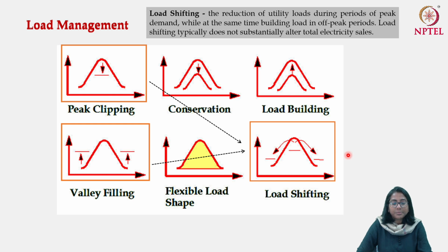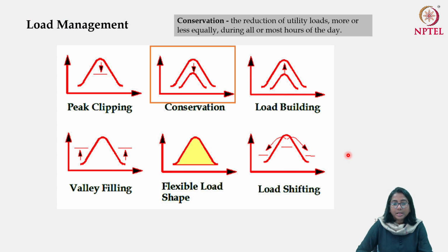So let me give you a quick example. Suppose you want a lot of hot water for bathing in the morning for the whole family and you have a storage geyser in place. So instead of switching on the geyser in the morning, you can actually switch on the geyser at night, where you are having some off-peak demand, let the water be heated and stored in the geyser, and use it the next day in the morning. So this is a typical example of load shifting. There are various other examples of load shifting as well, and this is actually studied deeply in the context of load management.